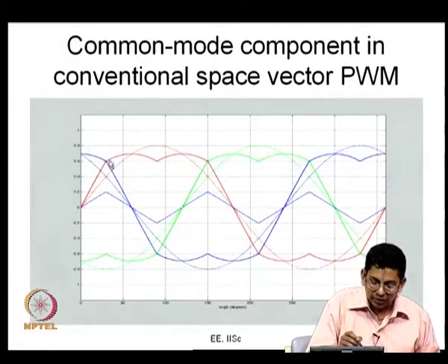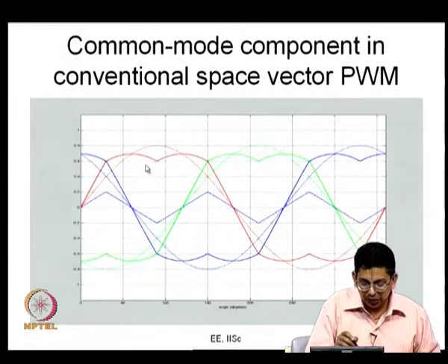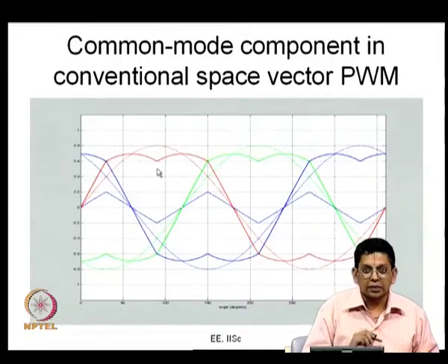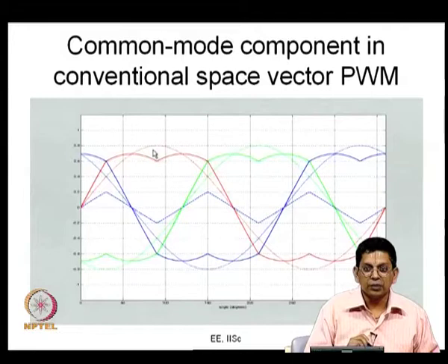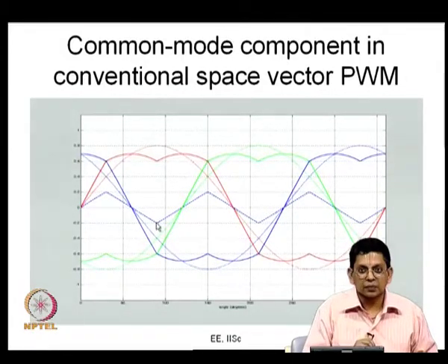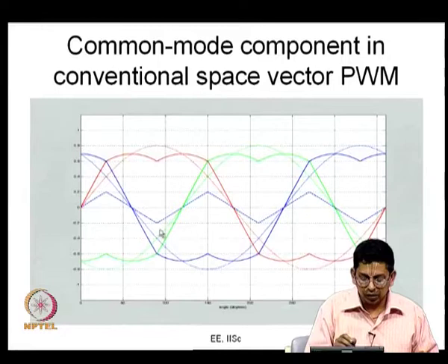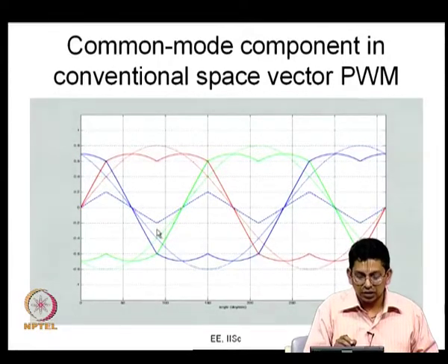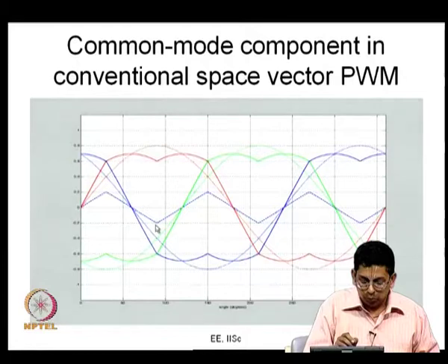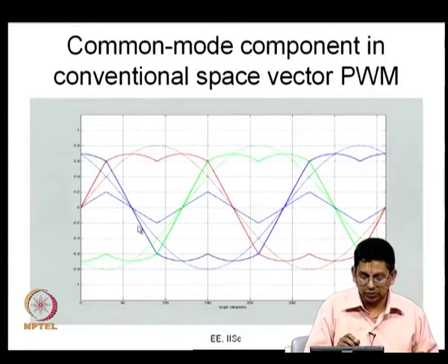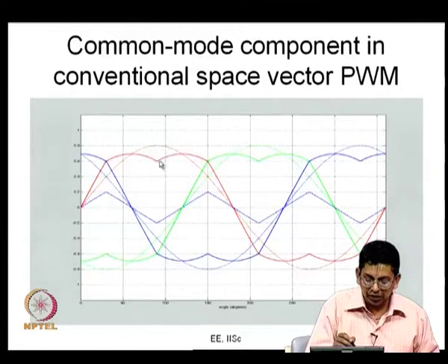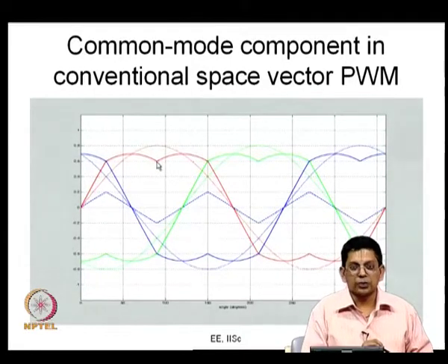So, you can see that here also, and what happens is then it becomes the same value, and here it is negative peak. So, when MR is having its positive peak and it is equal to Vm, MCM is having its negative peak, and this is how much? Vm, and how much is this? This is 0.25 Vm, this is minus 0.25 Vm now. So, Vm sin 30 is 0.5 Vm, so this is half of that, so it is minus 0.25 Vm. So, what you have here is something like 0.75 Vm is what you have there.